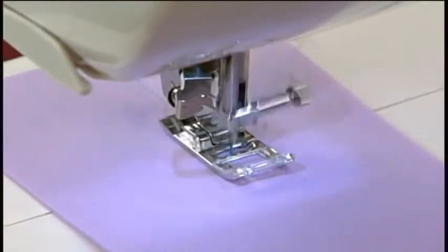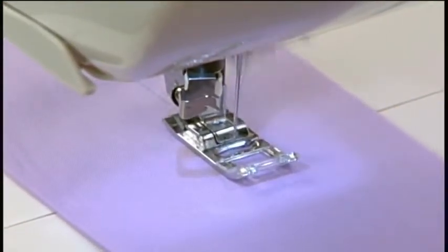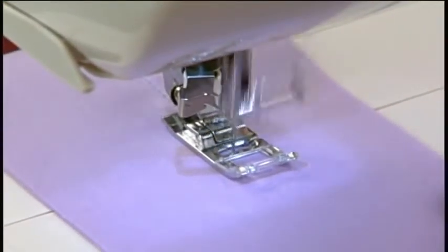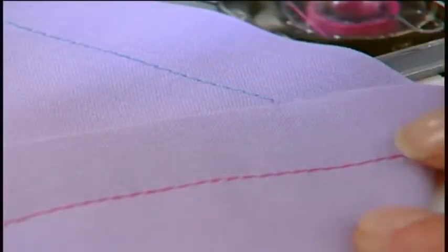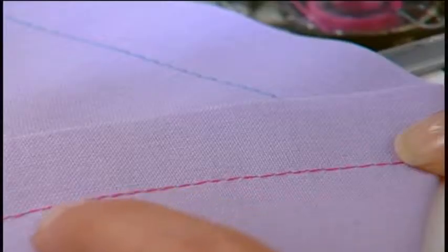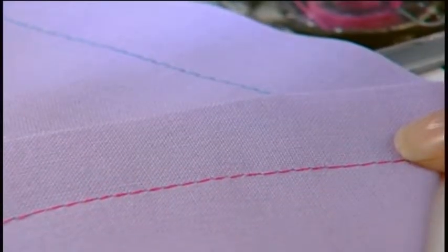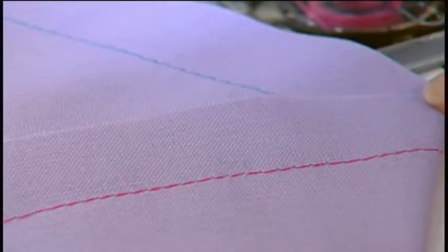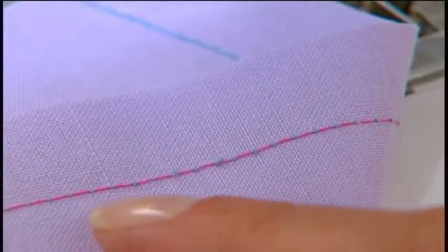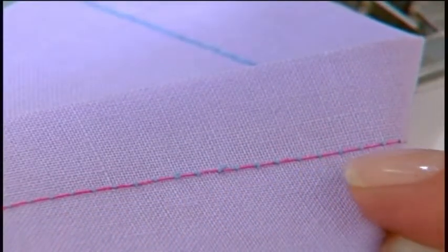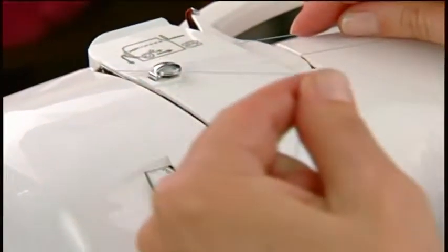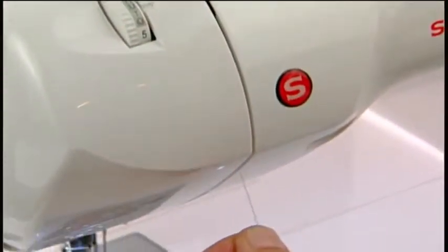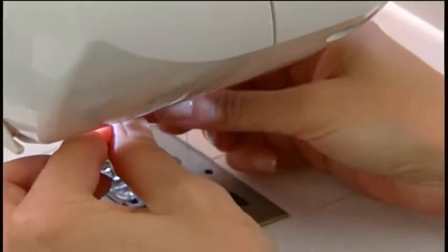The correct appearance of your stitching is mostly determined by the balanced tension of both top and bobbin threads. For straight stitch sewing, the tension is well balanced when these two threads lock in the middle of the fabric layers you are sewing. If, when you start to sew, you find that the stitching is irregular, you will need to adjust the tension control. Do this, however, only after you have determined that the machine has been correctly threaded.